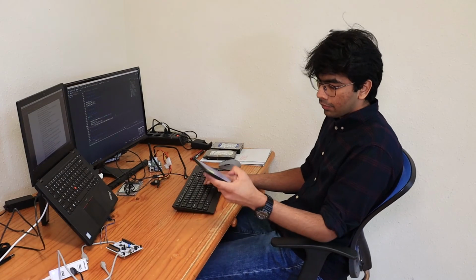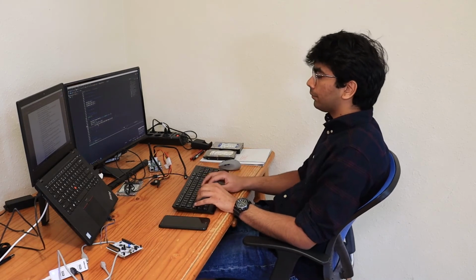You accepting the phone call and talking on the phone is basically the CPU or the microcontroller serving the interrupt in an interrupt service routine, or ISR for short. That is basically just a function written in C. And then you getting back to work is the CPU getting back to what it was executing before.